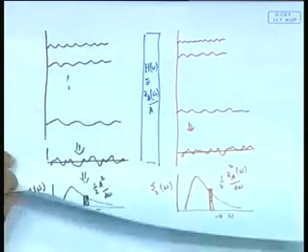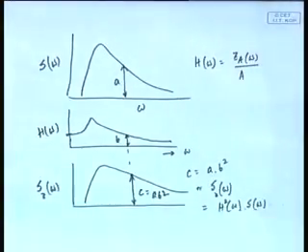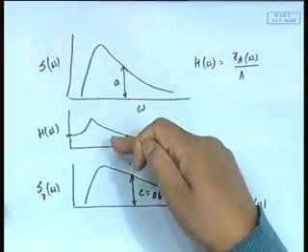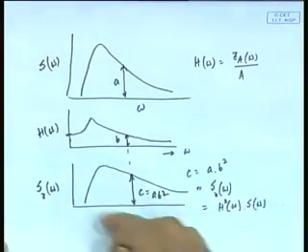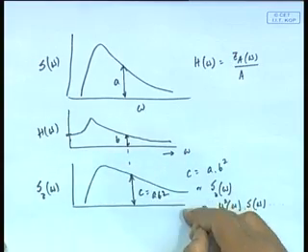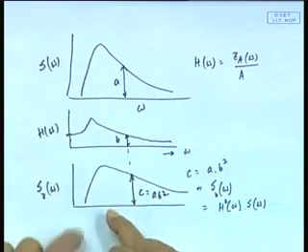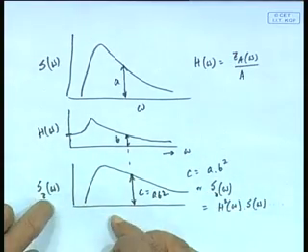So, you see, people are going to ask you how the ship responds in, let us say, sea state 3. So, what would happen? You start with sea state 3. I know H 1/3, I have a formula for this, then I have got this from a different source, I combine them, and I will say in sea state 3 my heave motion response is this, the spectrum is this. This is what is known as the response spectrum.